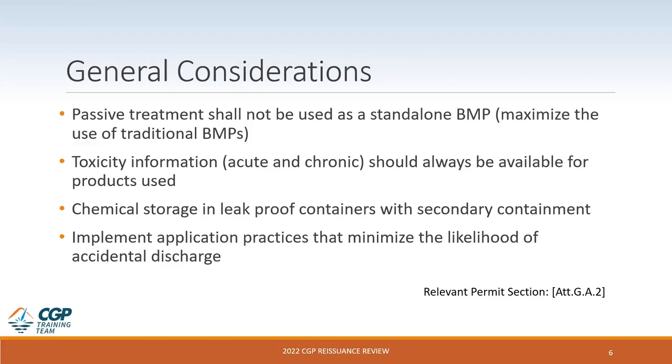So a few general considerations when discussing passive treatment technologies. One of the main points to highlight is that passive treatment should not be used as a standalone BMP. So it's really important on a construction site to first maximize the use of traditional erosion and sediment control practices, ensuring that you have appropriate erosion control and sediment control in place first, using those traditional practices before looking at a potential chemical treatment option.